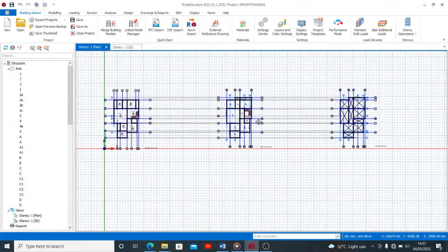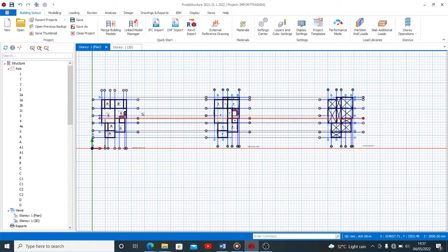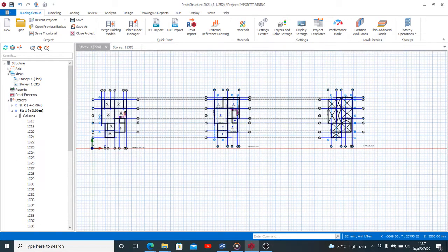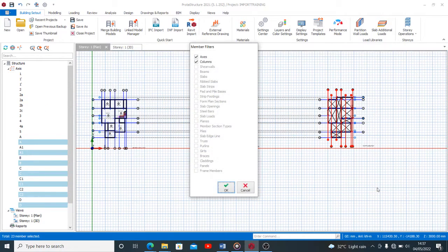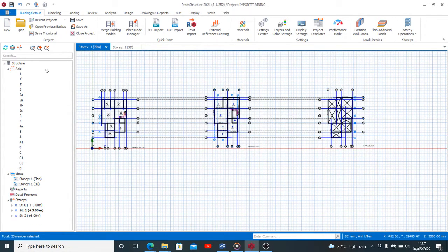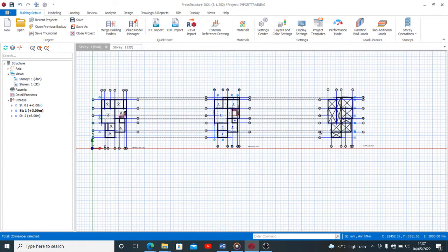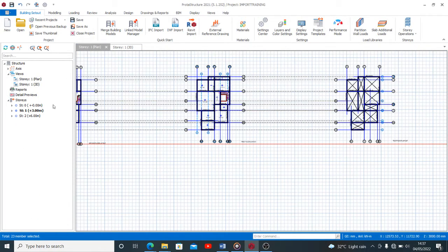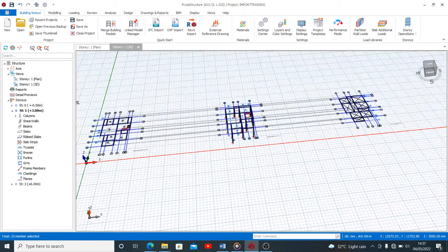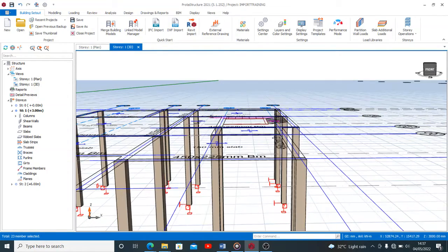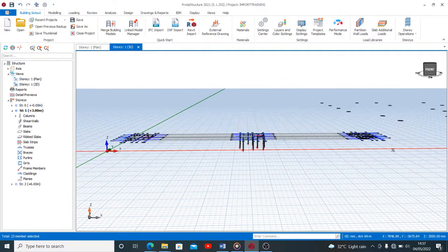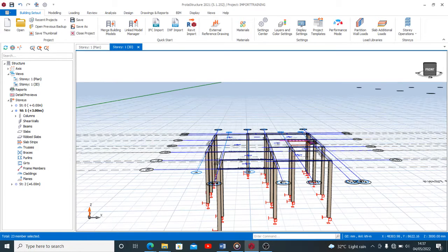Okay, and that's it. Now on this particular floor also, I would take away the details of story 02, since this floor is meant for story 01. So I'm taking all the structural components of all other stories away from this particular floor. Let us check the 3D model and see what I'm saying. You see that I'm only having this one right now, and the other two that used to be there that I showed you are no more there.